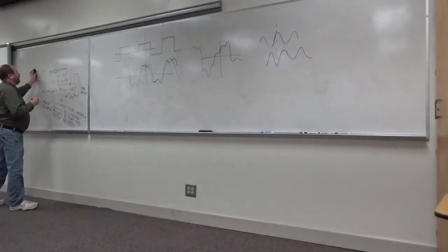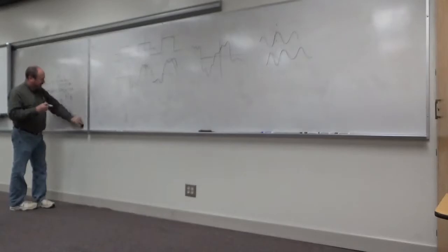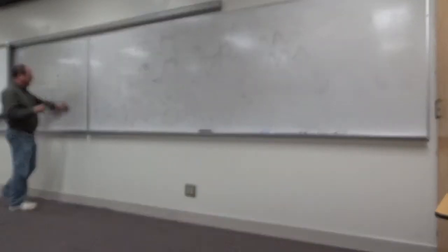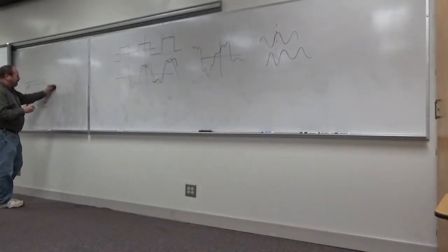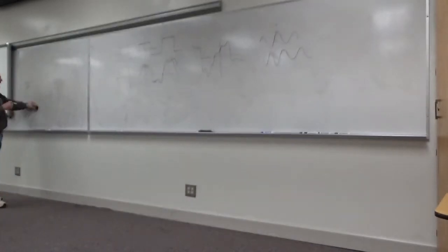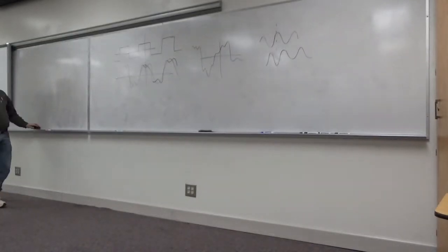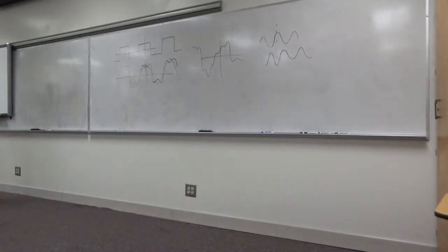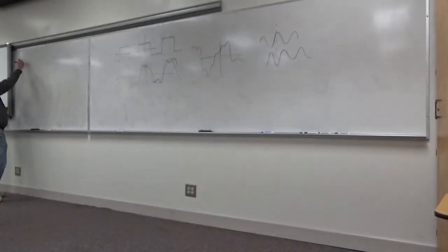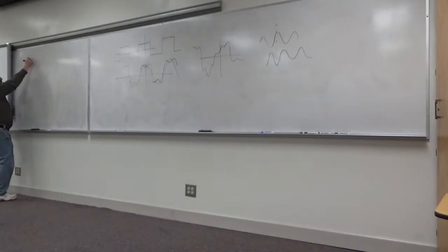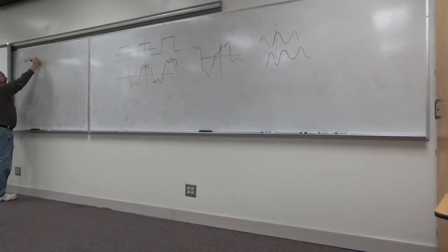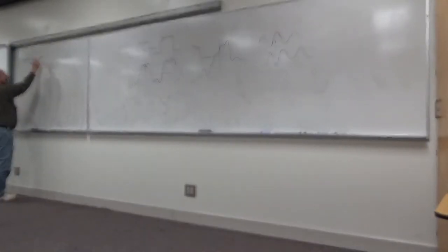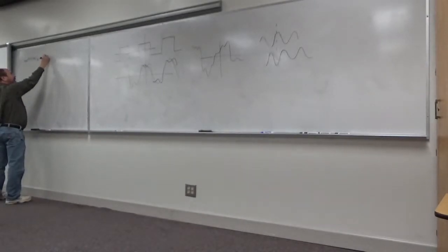Let's go on with this frequency response idea. And you remember talking last week or Monday, whenever it was, about distances to poles and zeros and all that as you go around the unit circle. We said H of e to the j omega is H of z evaluated at z equals e to the j omega. This is on the unit circle.